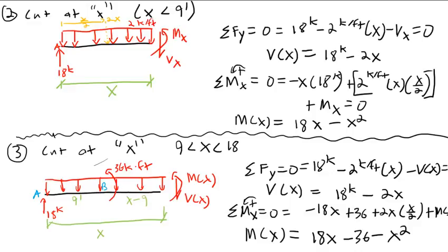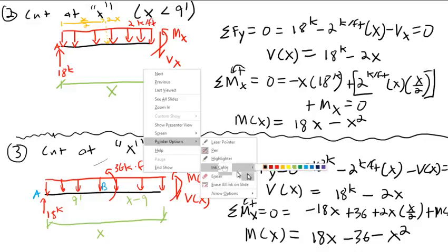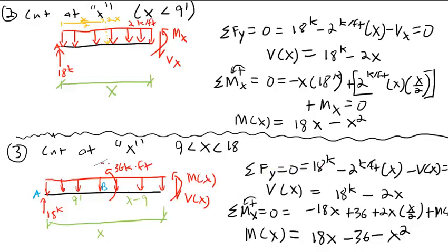And then the distributed load, all of this 2 kip per foot distributed load, let me actually label the 2 kips per foot on there. The total load of this is 2 times x. So if you had 12 feet or something like that, there would be a total of 24 kips there. And the centroid of that is going to be at x over 2. Again, you can use this for the purpose of finding external reactions, essentially.